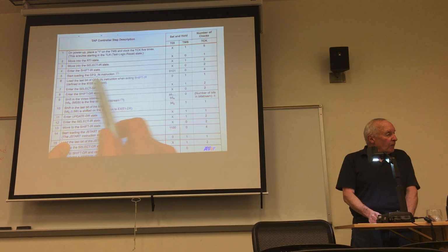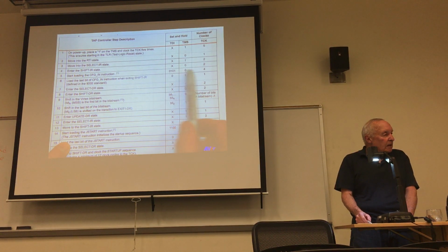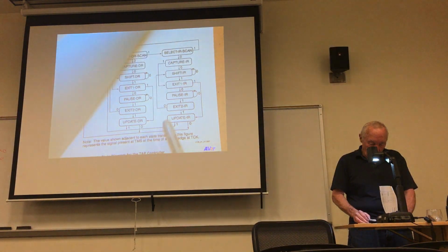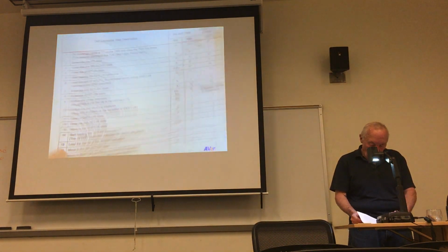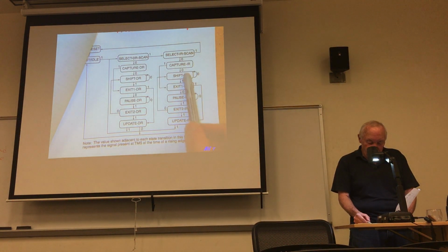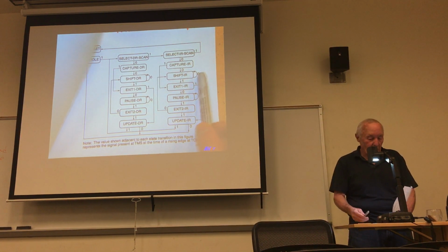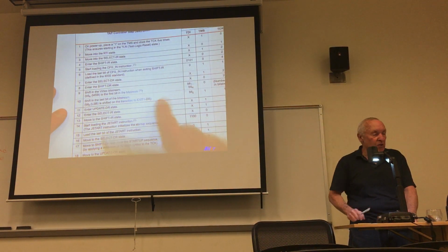Start loading the configuration instruction. I need to put 0101 on test mode select and give it 4 clocks. I'm in shift IR. Let's see, test mode select is a 0. So I'm going to stay in this state, but I'm going to clock 4 times, and test data in will clock in the new instruction. So you see how you can move through the finite state machine as you follow these instructions.